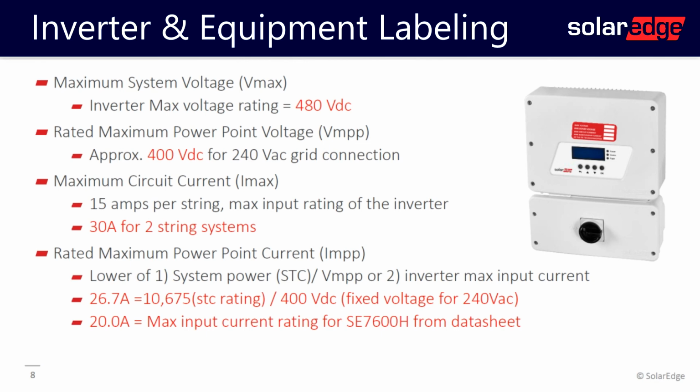The VOC is your open circuit voltage, and it is recorded for SolarEdge as our safe DC, which is 1 volt per optimizer. That doesn't tell us very meaningful safety information. So instead of VOC and ISC, we are going to write Vmax and Imax.